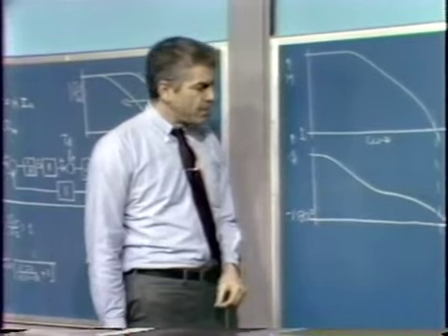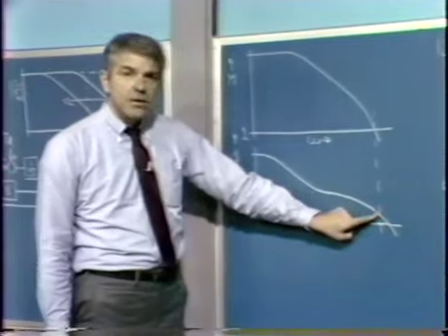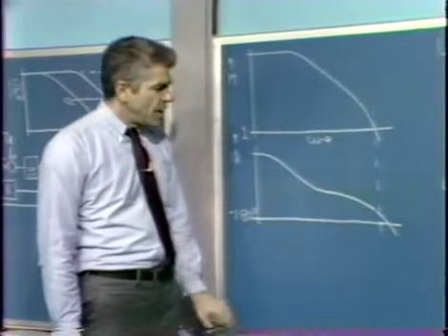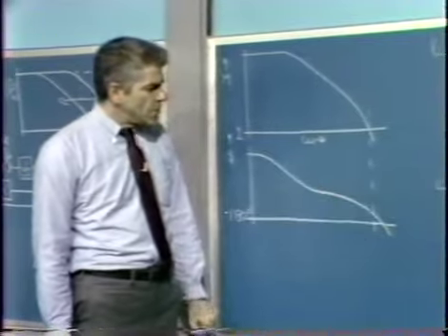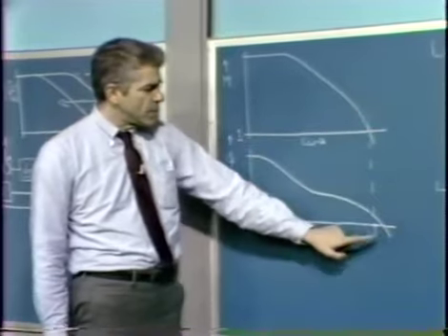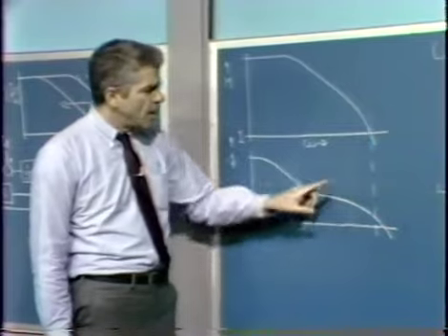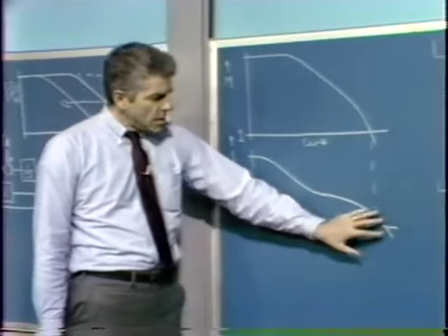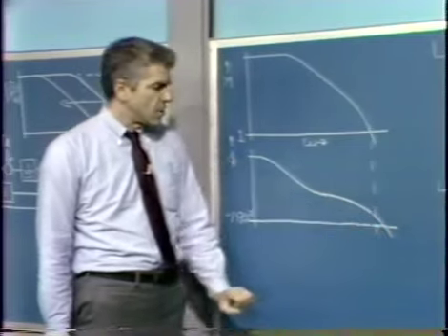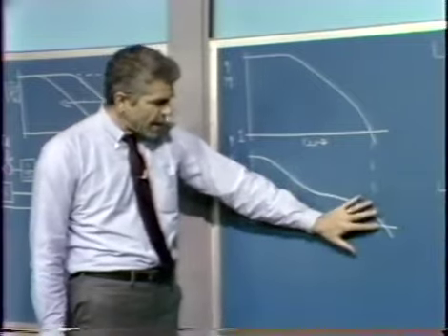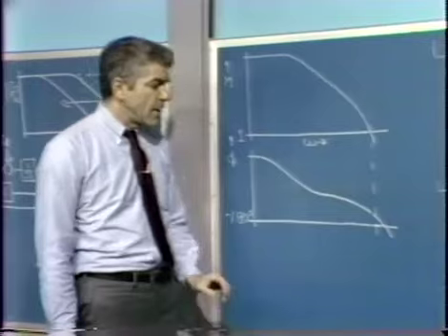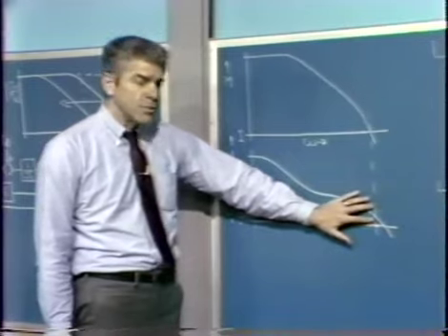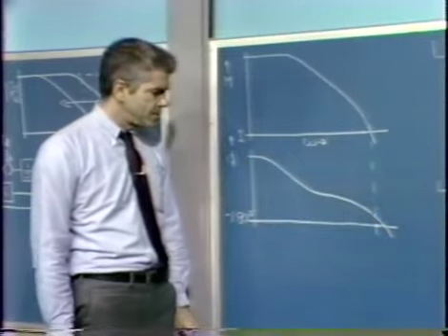Suppose we could do something to increase the angle associated with the transfer function, or with the loop transmission, out in this region. If we could somehow push up the angle, and do that in a way that didn't increase crossover frequency, so that we didn't get additional negative phase shift associated with the uncompensated system hurting us, but keep the magnitude the same out here, that would certainly help. If we could make this angle more positive, of course, we'd increase the phase margin of the system and thereby improve the stability. So that's one thing that we might like to do.